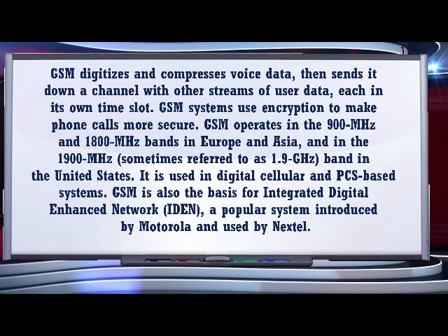GSM operates in the 900 MHz and 1800 MHz bands in Europe and Asia, and in the 1900 MHz, sometimes referred to as 1.9 gigahertz band in the US. It is used in digital cellular and PCS based systems. GSM is also the basis for Integrated Digital Enhanced Network, a popular system introduced by Motorola and used by Nextel.